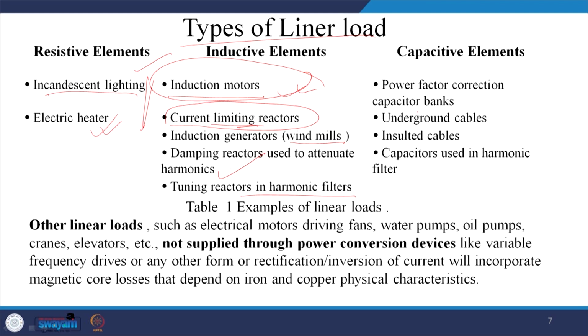And thereafter it can have a capacitor element. Mostly this reactive power is consumed in induction motor drives, and to mitigate this we have a solution, that is a power factor correction capacitor bank, but that itself is nasty. We will discuss the effect of the capacitor in one chapter itself.